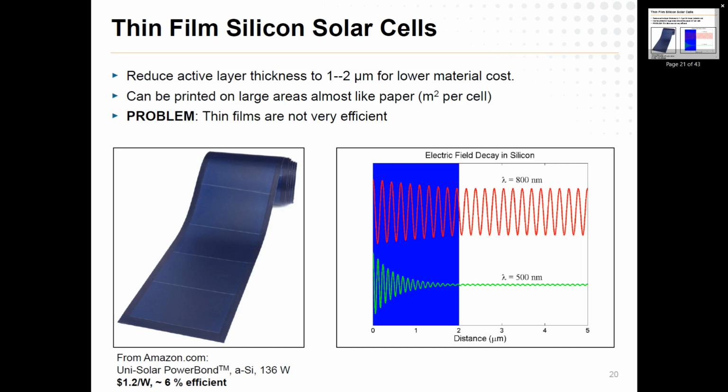For example, instead of manufacturing giant panels, it comes out of these sleeves, almost like paper towels. One of the analogies people often describe is that when you go thin film, you're not really creating solar cells in integrated systems, you're almost printing it like a newspaper. The efficiency, of course, goes way, way down, 6% efficient. Part of that's because it's amorphous silicon, not crystalline, but part of it is because it's just so thin. But the cost went way down as well. Before we were at 1.8, now we're at 1.2. So it's less efficient, but so much cheaper to make that you can just make more of it.